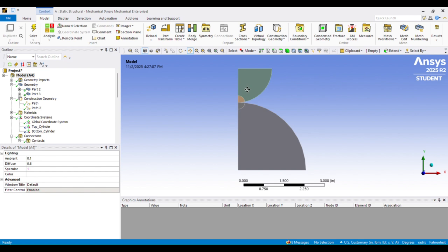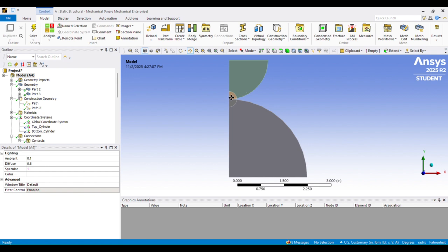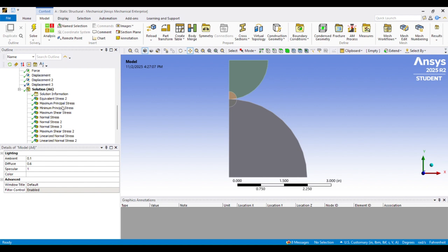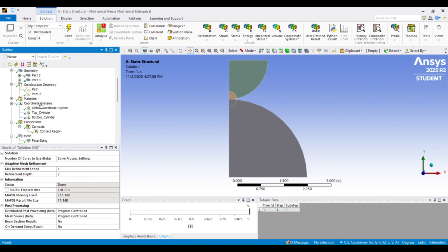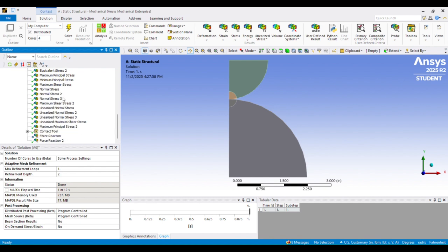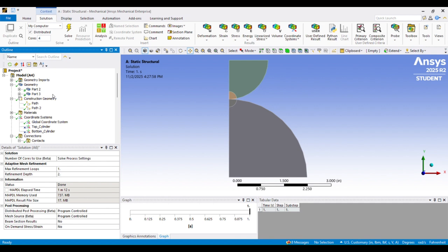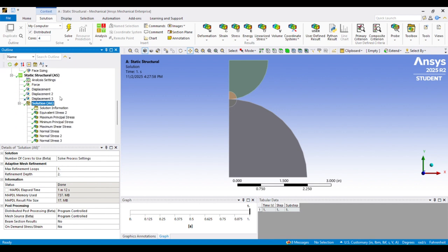But for our case, we're just going to use the displacements for symmetry. And then I've set up my stresses here. And then you can right-click and hit run, and you will get the stress results. All right, in the next video, we're gonna post process these stress results and compare them to hand calcs. All right.